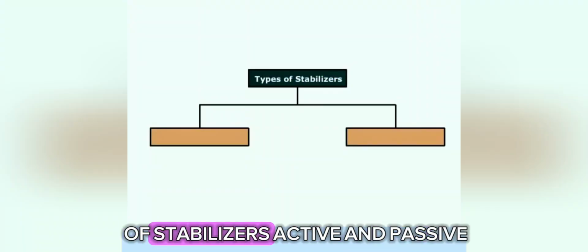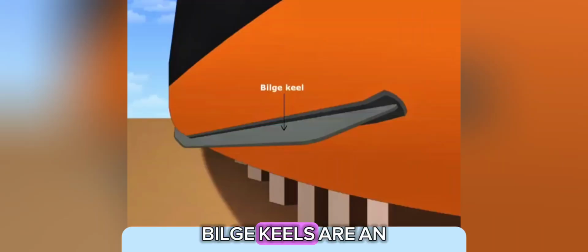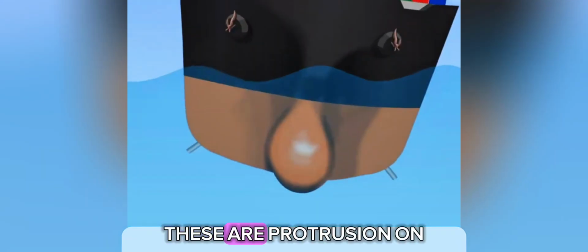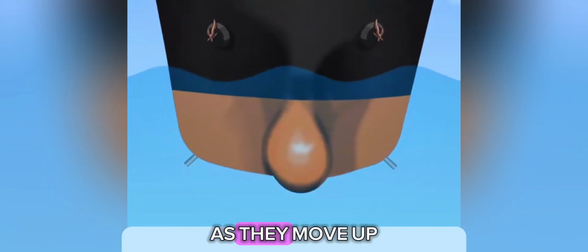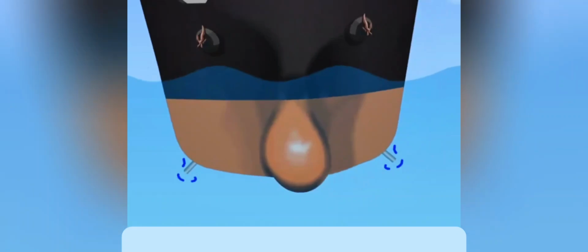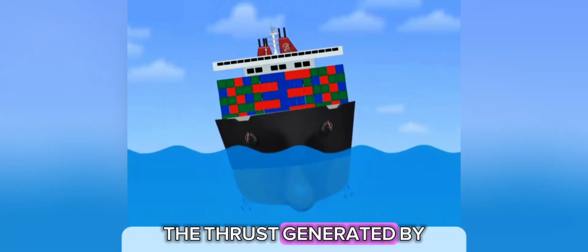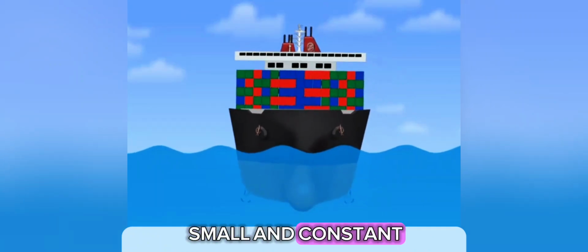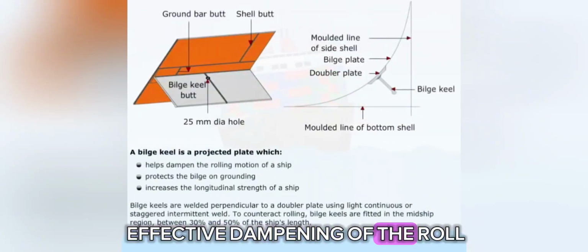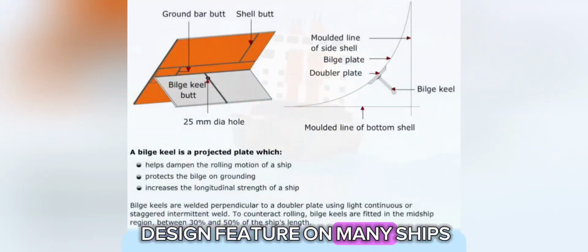There are two types of stabilizers, active and passive. Bilge keels are an example of a passive stabilizer. These are protrusions on the hull's bilges. As they move up and down along with the ship, they produce turbulence. Due to rolling, the bilge keel produces thrust which reduces rolling. The thrust generated by the bilge keel is small and constant since they are passive. Bilge keels do effective dampening of the roll, and they can be easily installed. Hence, they're a common design feature on many ships.